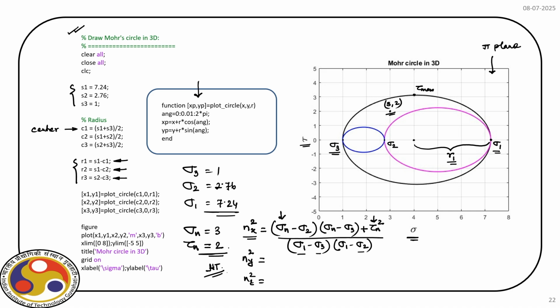So, that clearly explains how to start with the 3D stress field and then find out the principal stresses and then draw the Mohr circle. Then if you consider any point within that Mohr circle, say this one, we can easily find out the respective plane on which this stress sigma n and tau n are acting. Okay. In your practice problems, you will have similar problems that you try, and then if you have any difficulty, let us know. Okay. So, let us continue further.